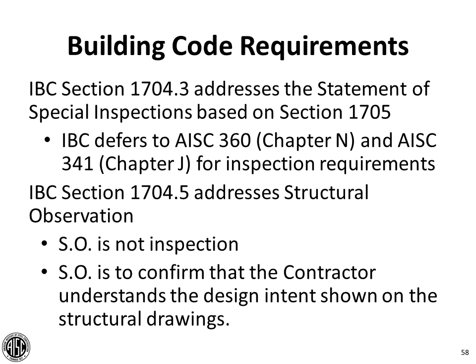And then in Section 1704.5, the IBC also addresses the issue of structural observation. And I wanted to draw a distinction between structural observation and special inspection. The idea behind structural observation is that it obligates the designer, most commonly, although another design professional can be designated as a structural observer. We don't see that happen very often, but it is permitted.